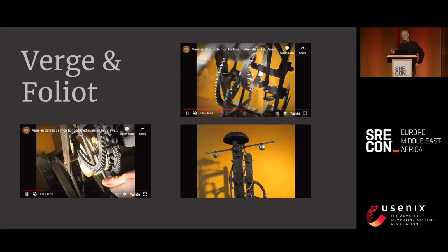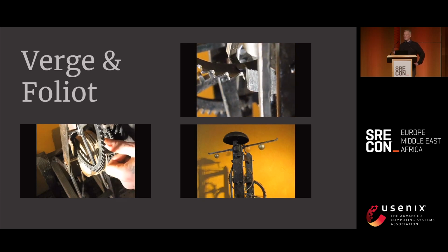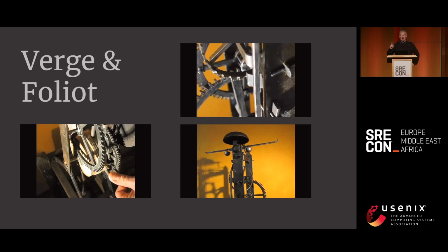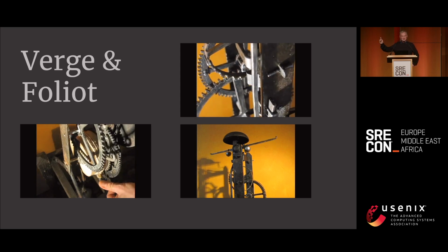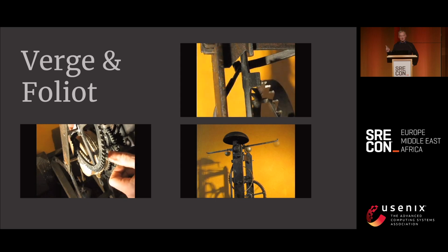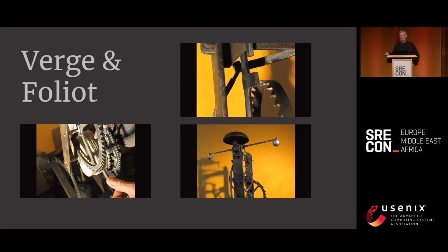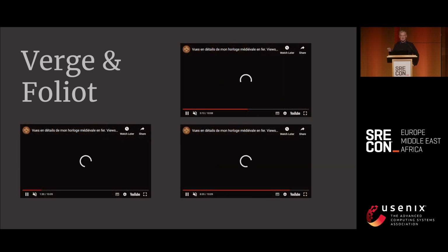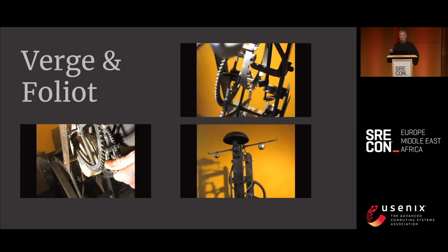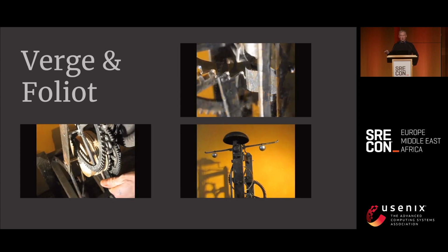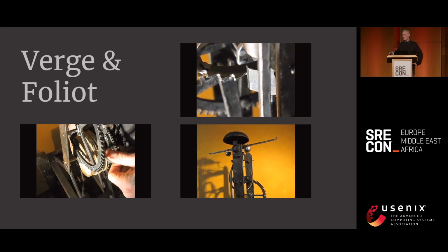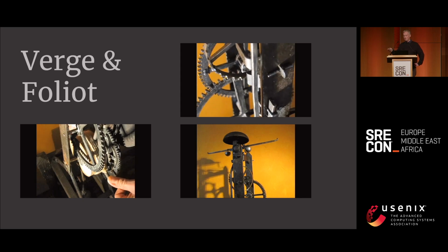The first designs for a mechanical clock use gravity for the energy source and an escapement to regulate the speed. There's one design I want to make sure we understand, so let's look at the verge and foliot. A toothed wheel spins because it has a coiled weight wrapped around its axis. But it can't turn freely because two pallets block its path and have to be pushed away. The regulator is a long arm with movable masses. The poor accuracy mainly stems from the friction between the constantly moving parts.